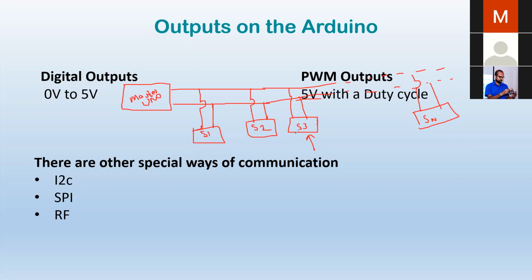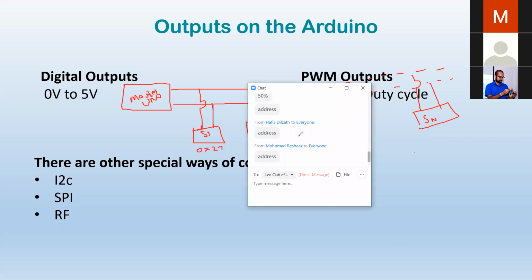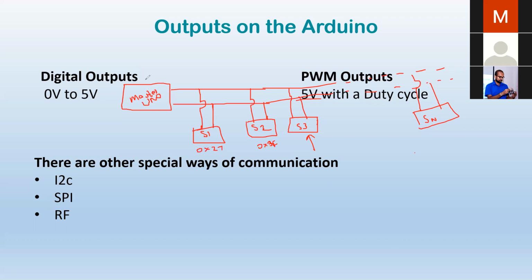What is unique of each house? The shape, of course, but the address. Yes, the address. So we give these things addresses. Usually they look like this, right? In I2C communication, we give these things addresses, and those addresses can be adjusted, of course.